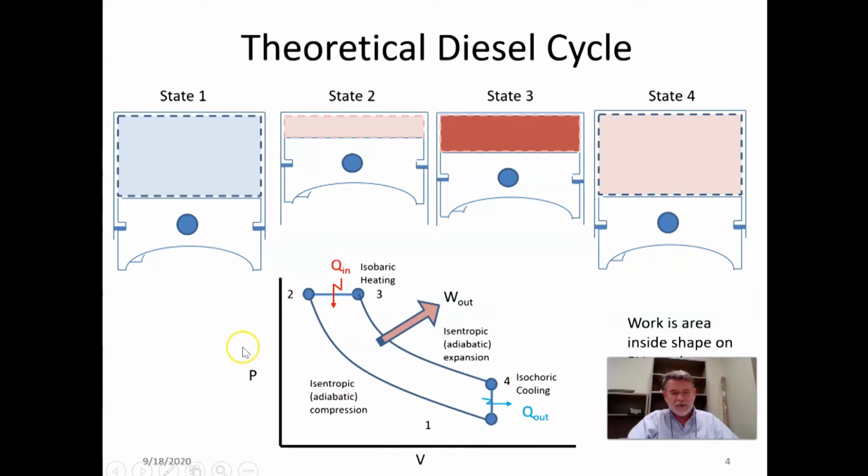That's a PV diagram, pressure volume diagram, which is always used for describing cycles like the diesel cycle or the Otto cycle, the one for gas and gasoline engines. But this one is a diesel cycle again. And so, back to what we were saying, here is the combustion. You see it's happening at constant pressure,